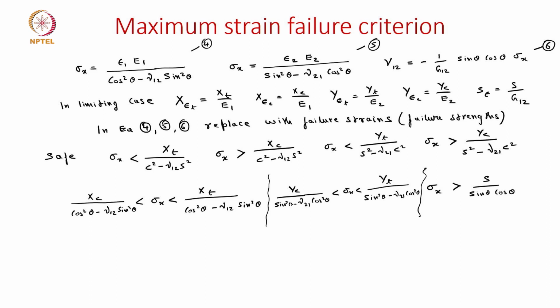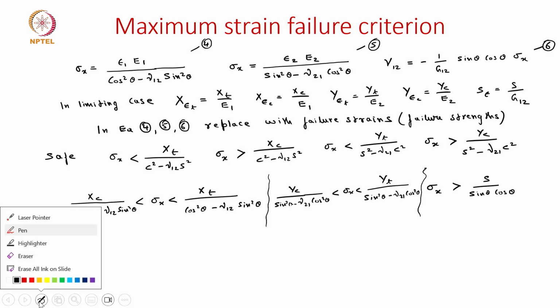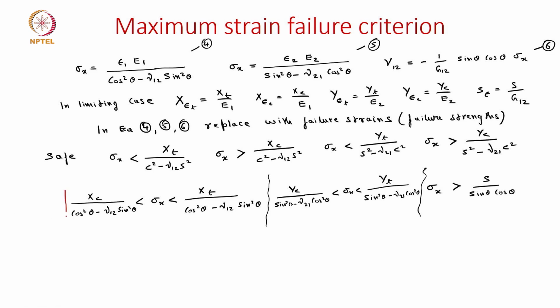Okay. So these are the final three expressions which we need to apply for the maximum strain failure criteria. And mind you, here we are only looking at when it is uniaxially loaded; sigma x is the only non-zero stress applied.